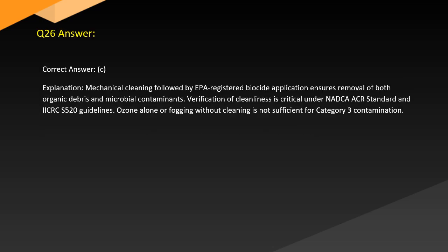Answer. Correct answer. C. Explanation. Mechanical cleaning followed by EPA-registered biocide application ensures removal of both organic debris and microbial contaminants. Verification of cleanliness is critical under NADCA, ACA standard and ICAC guidelines. Ozone alone or fogging without cleaning is not sufficient for Category 3 contamination.